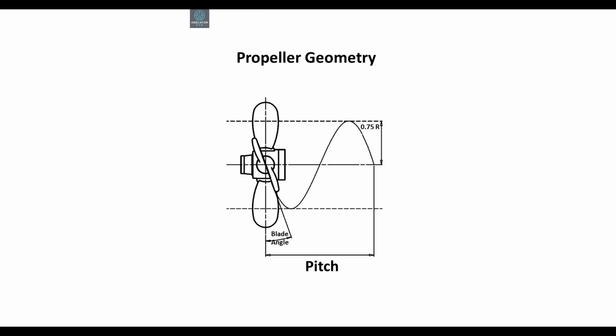Propeller blade sections are typically based on airfoils. Airfoil shapes are defined using several parameters. The most important parameters are chord, thickness, and camber. With few exceptions, the blades of a propeller are identical and repeated. Therefore, it is sufficient to create only a single blade geometry and then generate the full propeller geometry by repeating and rotating the blade around the propeller rotation axis.